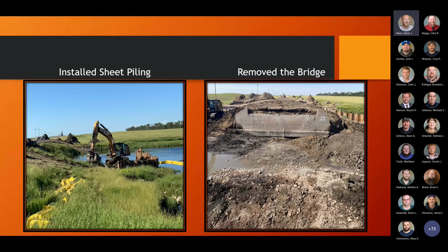After the diversion was completed, the contractor then worked on finishing the sheet pile around the site. Once sheet piling was done, they then set up a 6-inch pump and drained the area. When they drained the area, they ran a hose up the ditch to pump to a filtration site that was made up of fabric, small rock, and fiber rolls, before the water could then work its way back to the channel.